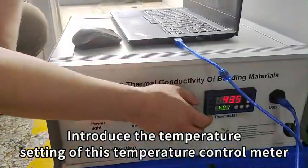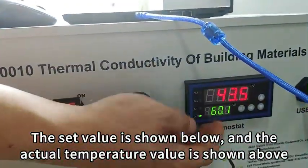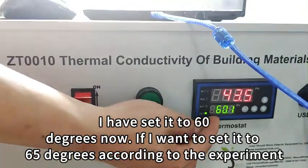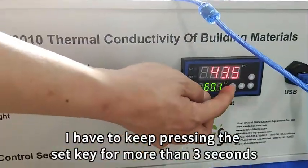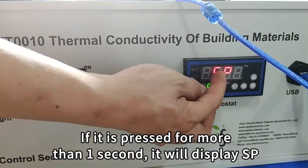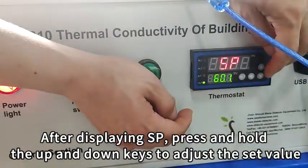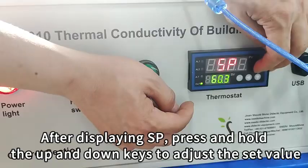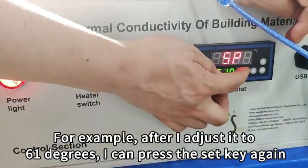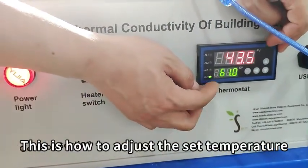Introduce the temperature setting of this temperature control meter. The set value is shown below and the actual temperature value is shown above. I have set it to 60 degrees now. If I want to set it to 65 degrees according to the experiment, I have to keep pressing the set key for more than 3 seconds. If it is pressed for more than 1 second, it will display SP. After displaying SP, press and hold the up and down keys to adjust the set value. For example, after I adjust it to 61 degrees, I can press the set key again.